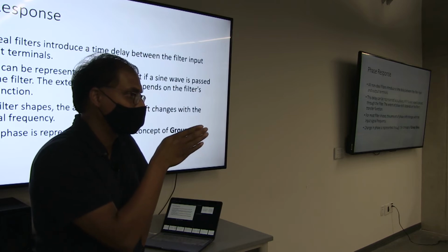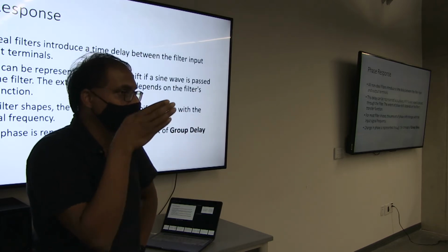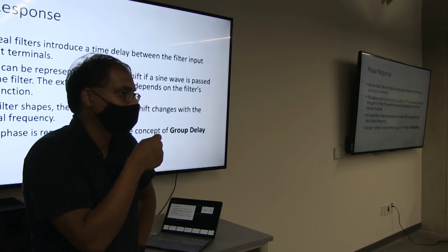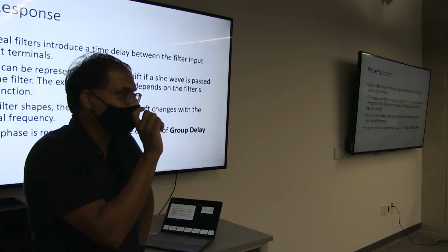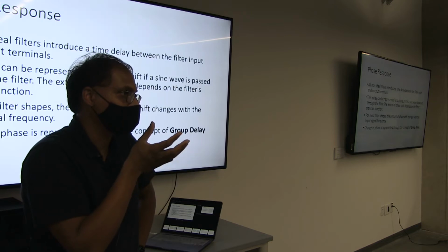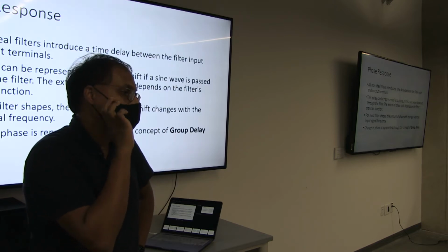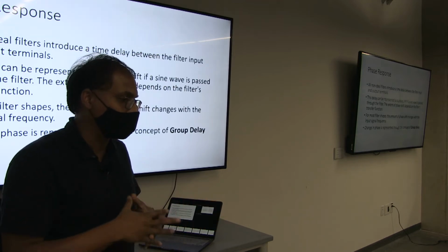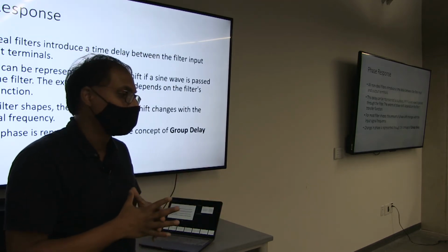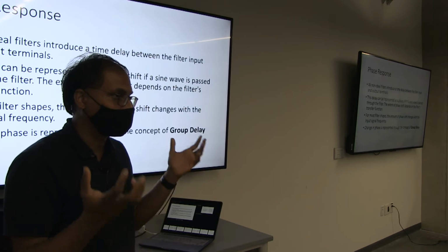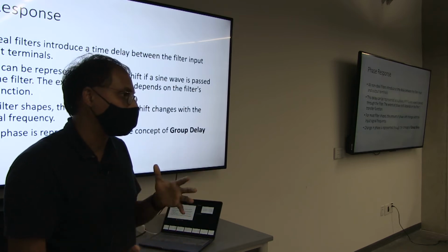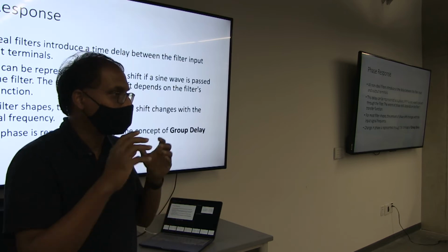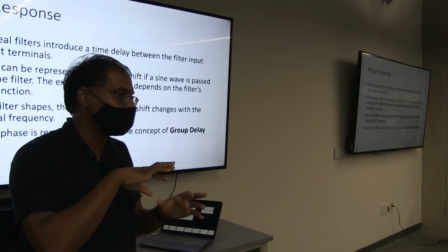So for example, if your pole frequency is 10 megahertz, the filter is very effective till 1 megahertz, because till 1 megahertz there is no phase shift, it is 1 decade below. Between 1 and 10 you will be seeing phase shift. So whenever you are giving an input signal between 1 and 10, we need to be cognizant of the fact that there is some phase shift involved. If we can tolerate that phase shift, we are okay, or not. If we need to choose some other filter configuration, or we need to come up with a scheme where we can compensate for the phase shift.